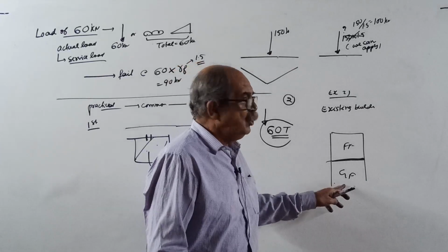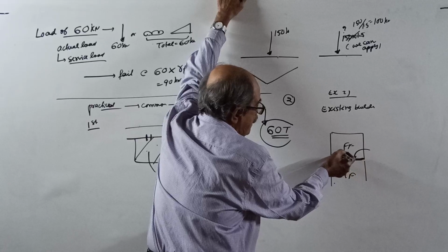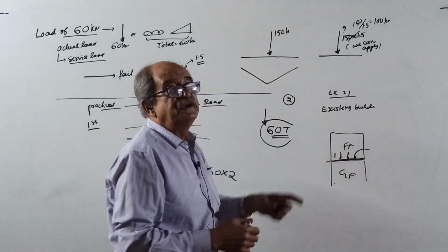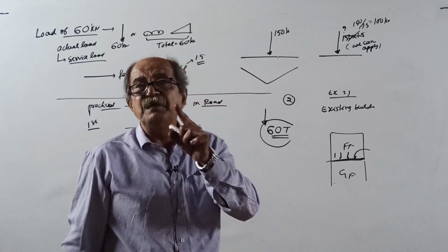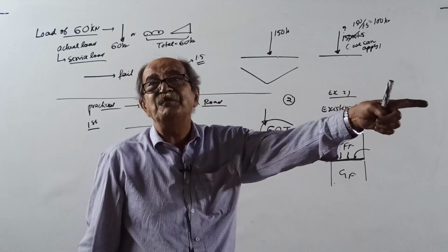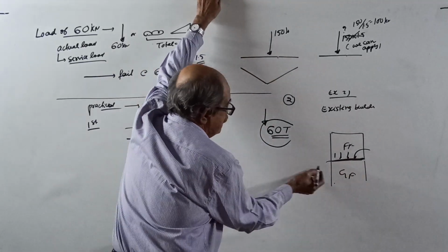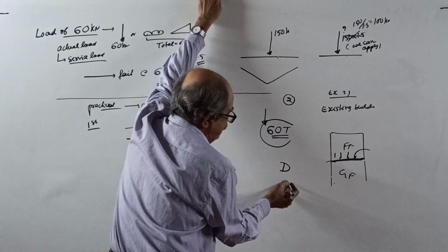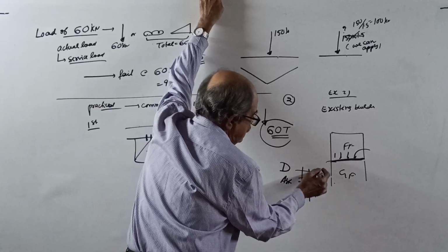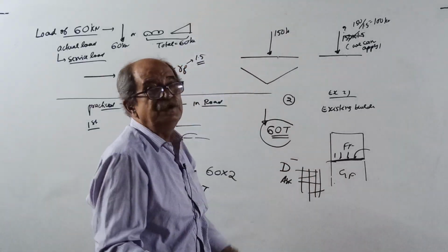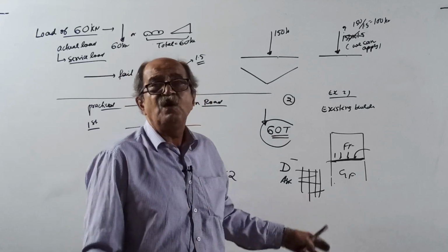He told some weight. Okay, then you go to your structural engineer and say, see, this floor I am going to rent out to some industrialist who is going to store something there. Please tell me, when the agreement is made, how much I should permit him. For that, your structural engineer will see the depth of the slab, what is the Ast provided, lengthwise and widthwise, etc. All the steel he will check, and which grade of concrete was used. The drawing is of an existing building, constructed last year, so structural drawings are there.